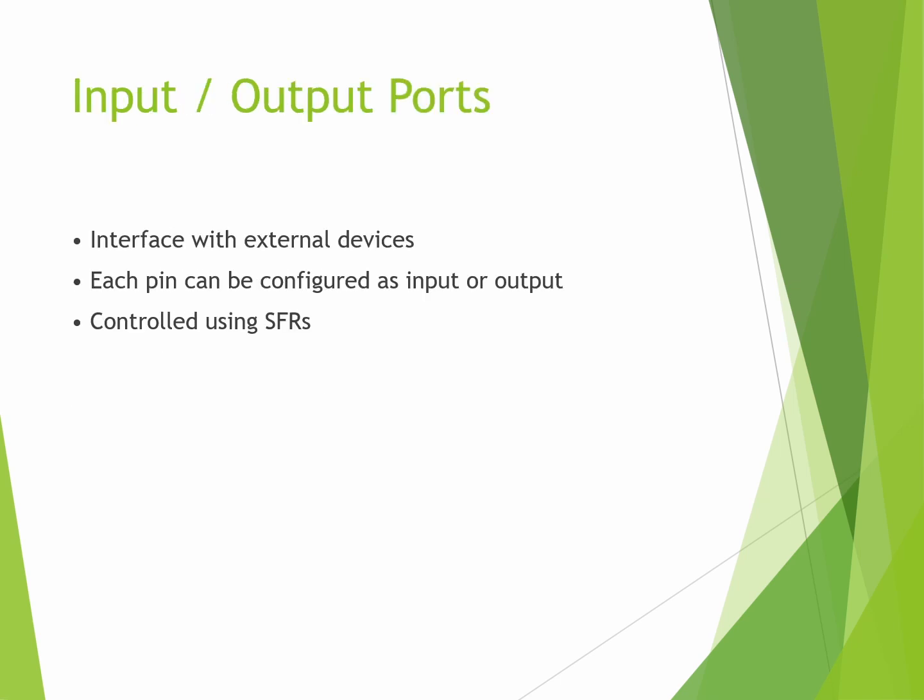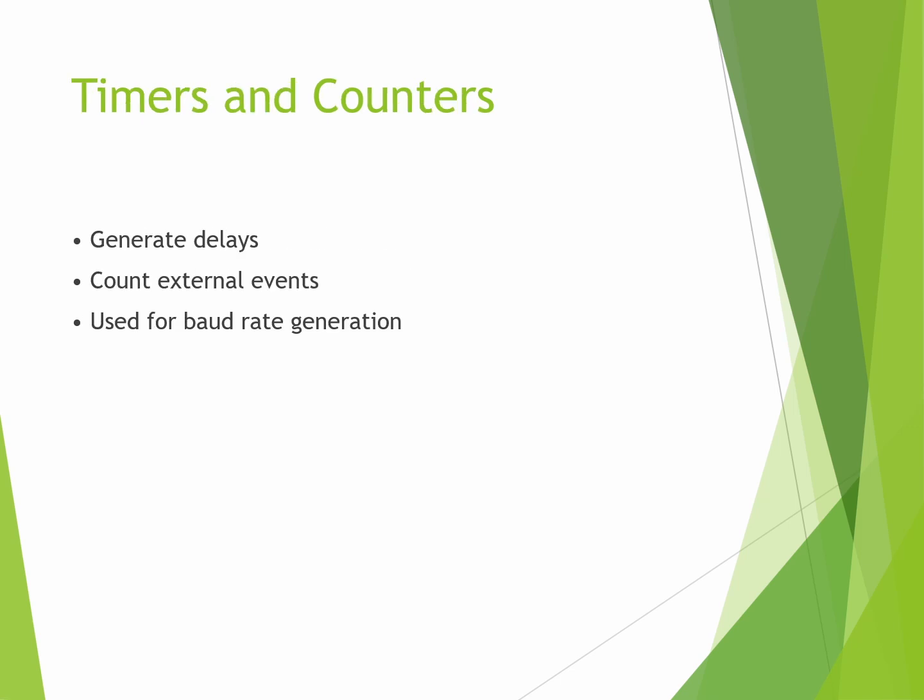Input and output ports. Input and output ports are mainly used for devices connected to external sources of inputs. Each pin can be configured as an input or output. In the pin diagram of the 8051, each pin is specified with input and output ports. It is controlled using SFRs, special function registers. Next is timers and counters. Timers and counters are used to generate delays. Generating delays is performed by the timer, and the counter performs counting of external events, which is used for baud rate generation.